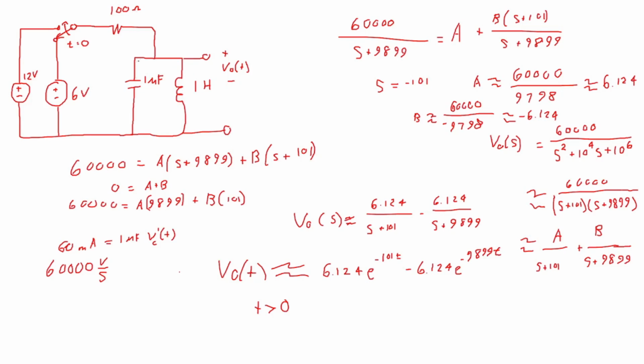And so the current from the capacitor actually begins to flow out the top, decreasing the voltage on the capacitor, and the inductor increases its current. And as it does so, the capacitor supplies some missing current with the resistor to meet the current request of the inductor under the voltage it has.